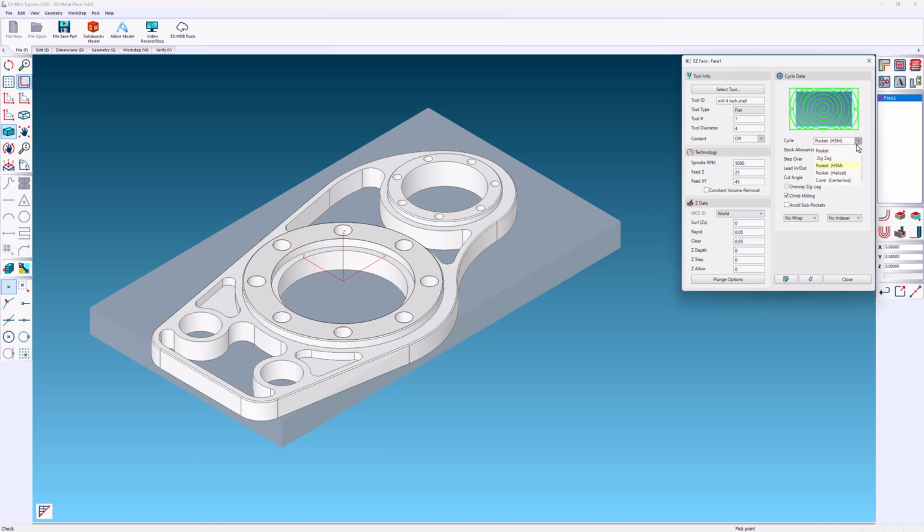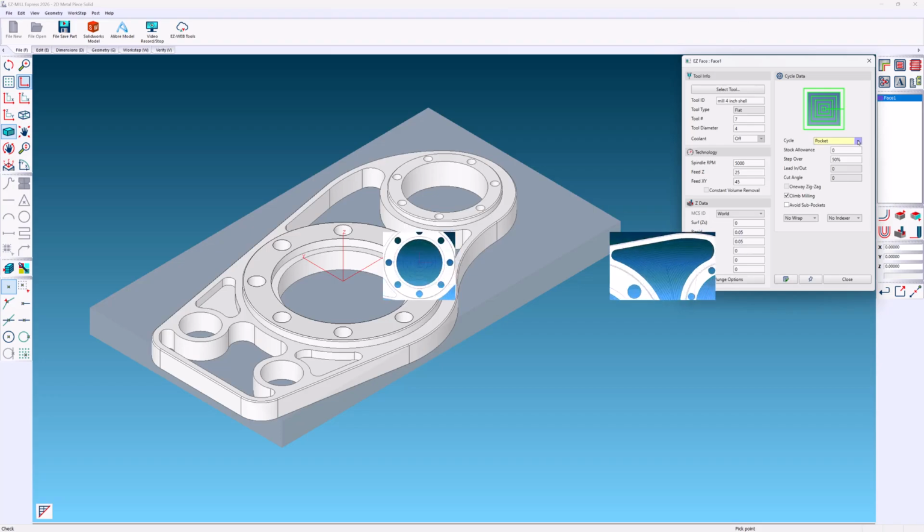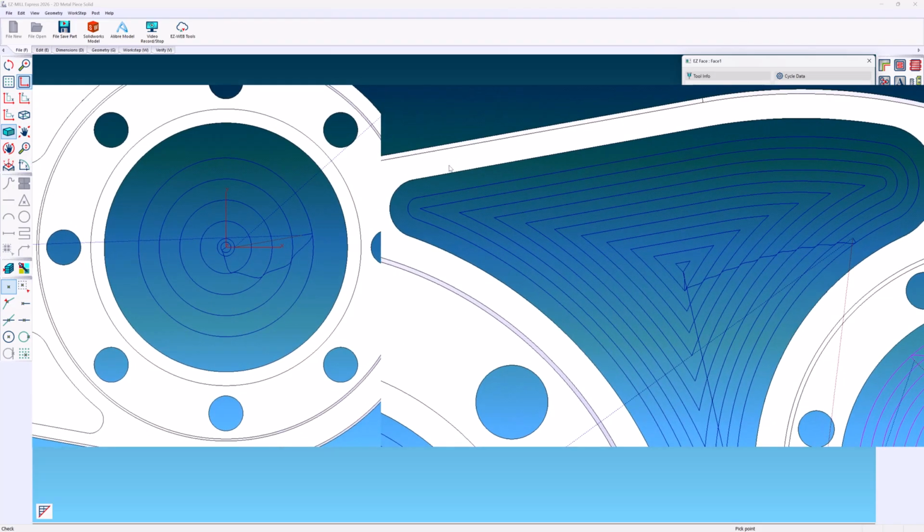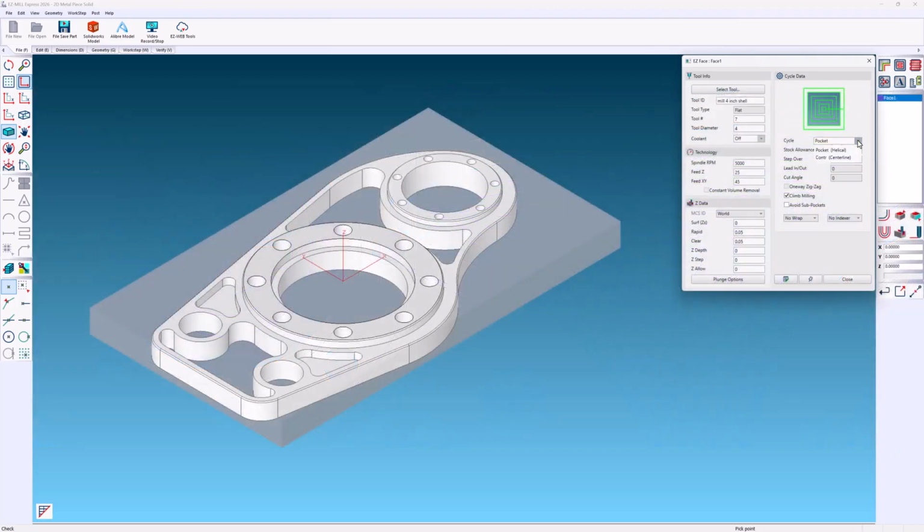Let's talk about the types of toolpath we can choose from, starting with pocket. Here you will see the cutter takes a full sweep around in the shape of the boundary, starting on the inside or outside, your choice. The step over is in the form of a stretched letter S, rather than in the shape of the letter L, which in the past would cause a hard stop.